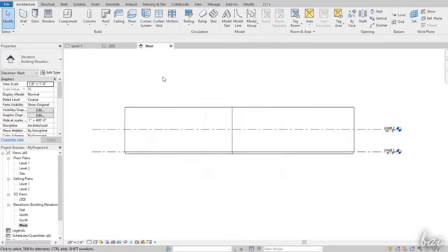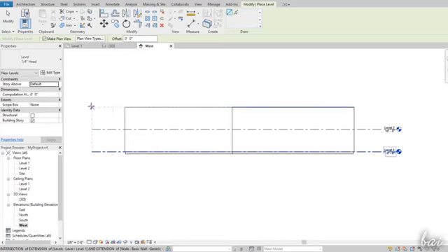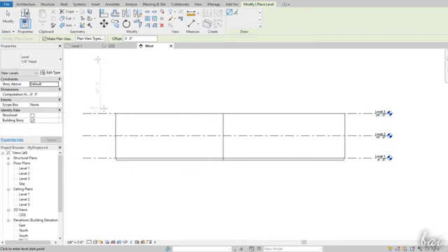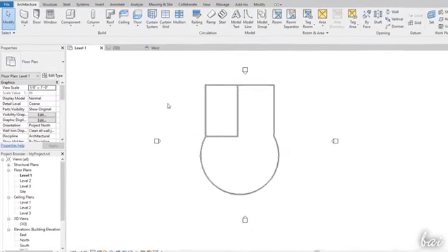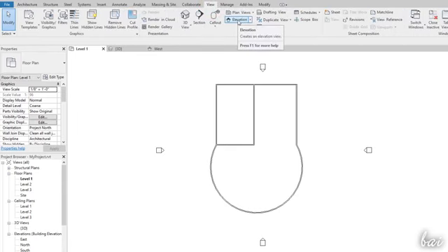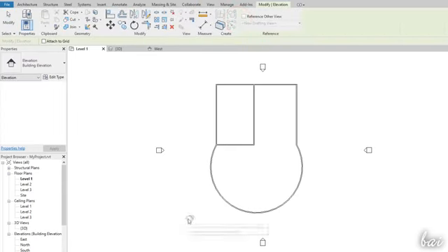You can also create new floor plans and elevations. To create a floor plan view, open any elevation view and then go to Level under the Architecture tab. Then, fix 2 points to define the height level and use the Escape key to apply. Whereas to create a new elevation view, open any floor plan view and use Elevation under View. Place the elevations needed and use the Escape key.